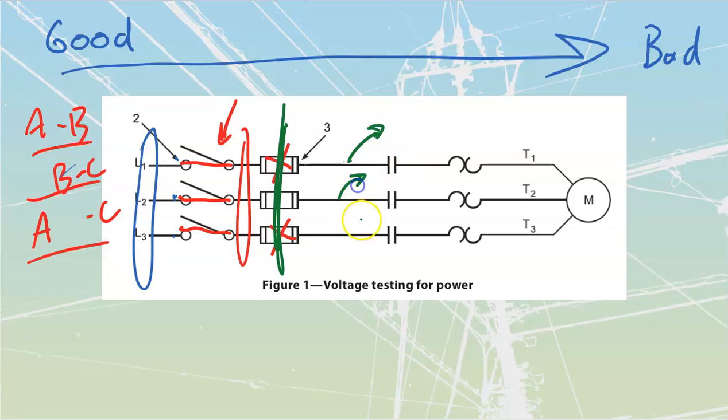See, with this one, I'd test that one line to ground, this one to ground as well, because that contact is open and the fuse holder is out over here. That switch should be back open as well. That would just mean that I'm going to be able to figure out whether these are short to ground. Then I'm going to do the same thing on the downstream side.